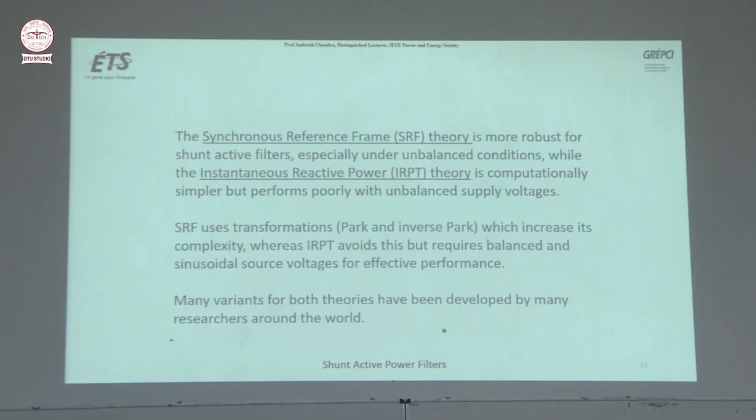But what can you say theoretically? Sometimes I feel that these two theories are sufficient for us. Synchronous reference frame theory is theoretically more robust for shunt active filters, especially under unbalanced conditions, if the supply voltage is unbalanced. The instantaneous reactive power theory is computationally simpler, but performs poorly with unbalanced supply voltage.